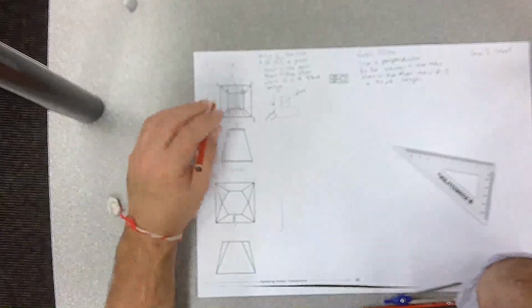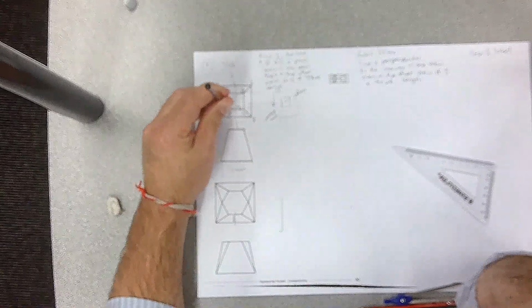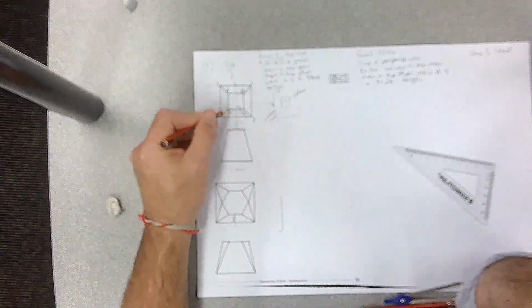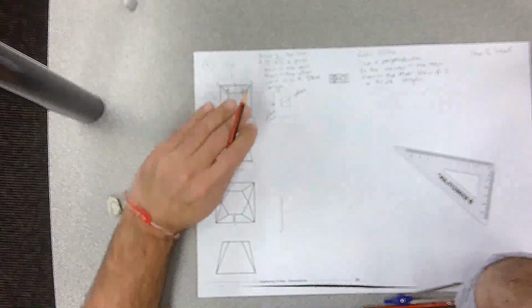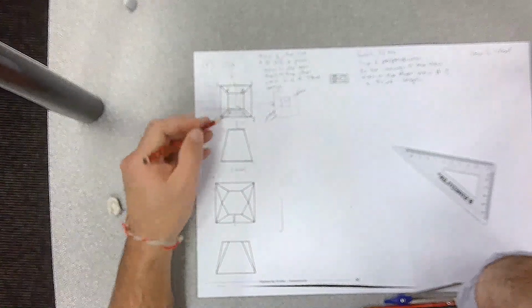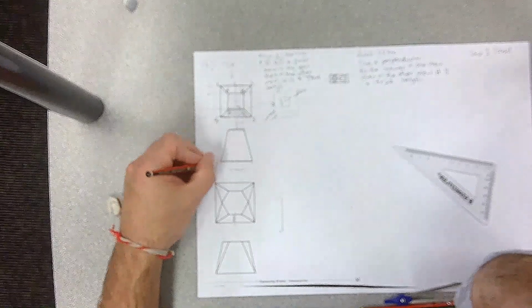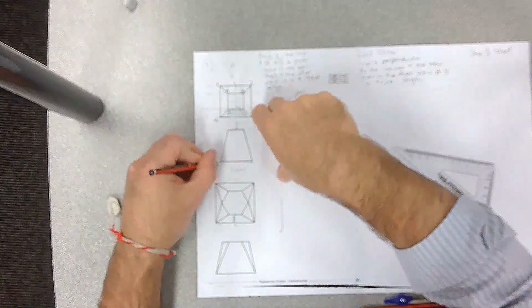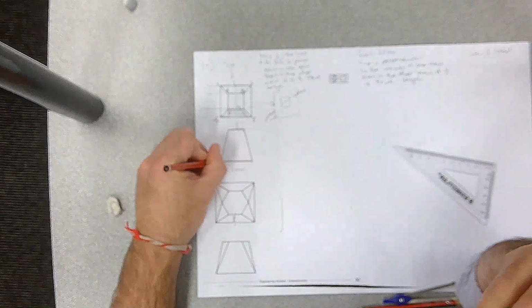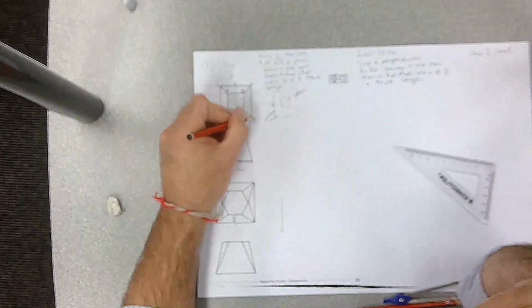Now when you take this object that you've got a top view and you tilt it up so you get a front view, which means you're looking at this bit here, what's going to happen is you're going to see an end view of this line here, and that's what we write down on this corner here, 1 and 4. That's a point view. So if it's a point view in this view, then 1, 4 is a true length in this view. And this is a point view as well.